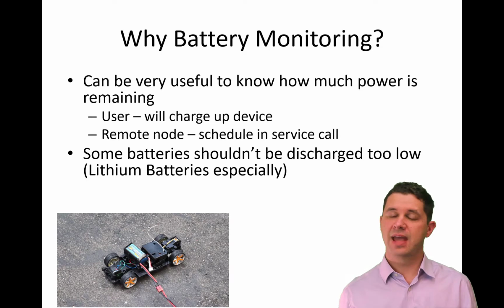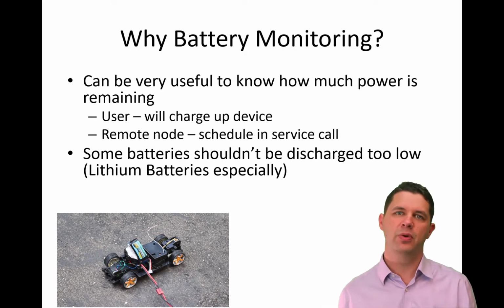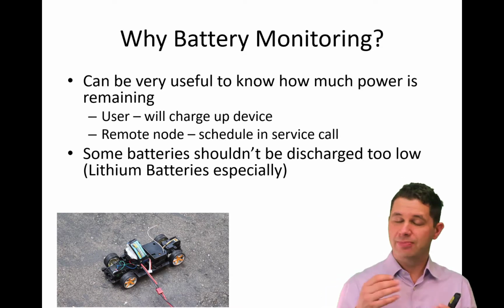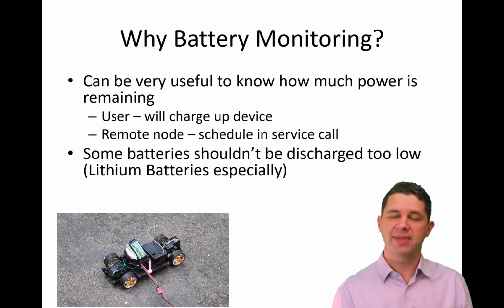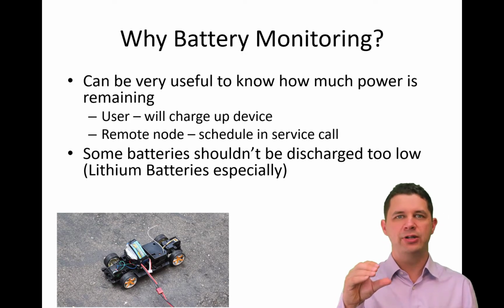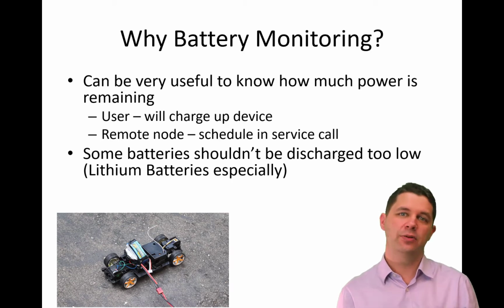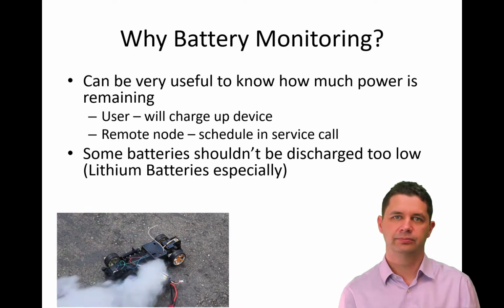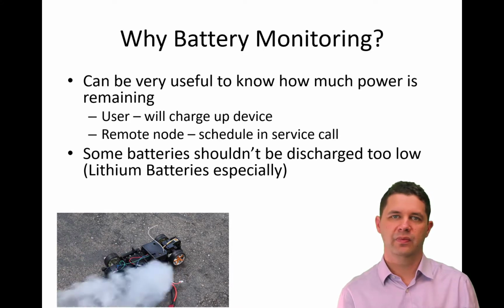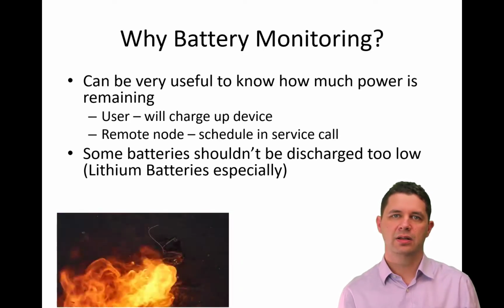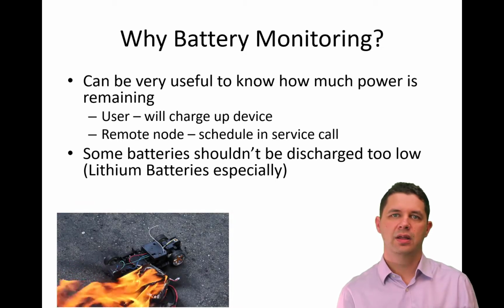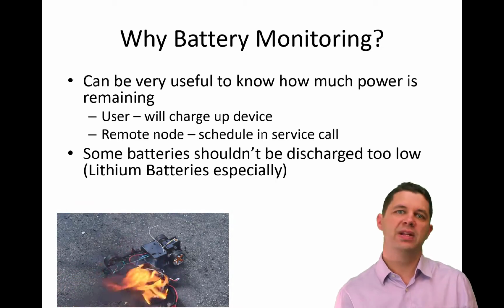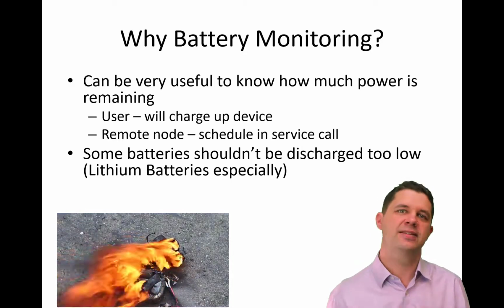One of the things, and these are lithium polymer batteries, it's a big problem with them in particular. If you discharge them too much and then try and charge them up, they start ballooning out, getting larger and larger and larger, and they can catch on fire as well. So we'll see an example of this. So that's what you don't want to happen in your mobile phone or your laptop, particularly while it's in your hands.